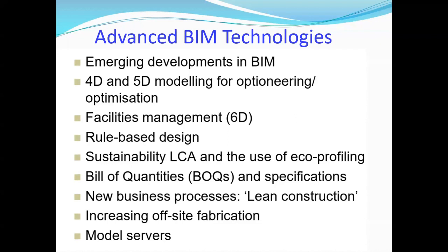Each point has its own coordinates. It's a global coordinate system, not a local one. In Singapore, after we do the site surveying, we can include our topo into the model. Then it contains the global coordinate system. Actually, you can put it in Google Maps. It's that precise. Each point contains the global coordinate, so you can merge or bind together to make one model.